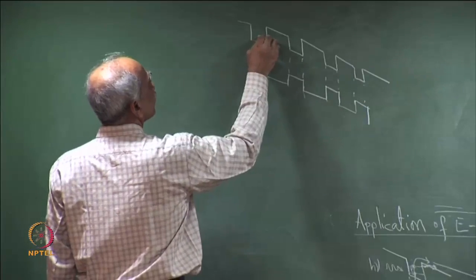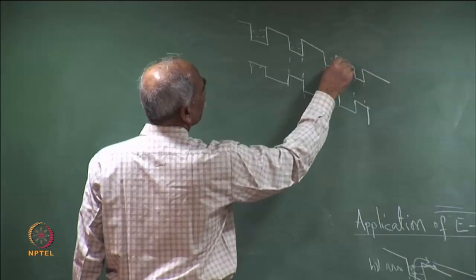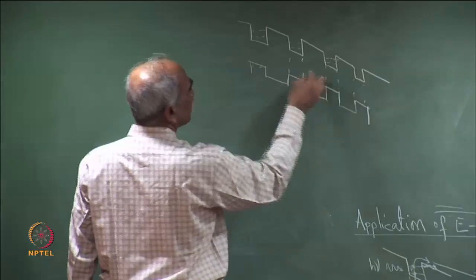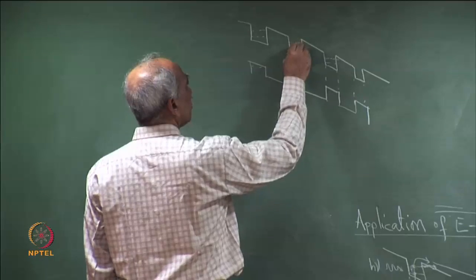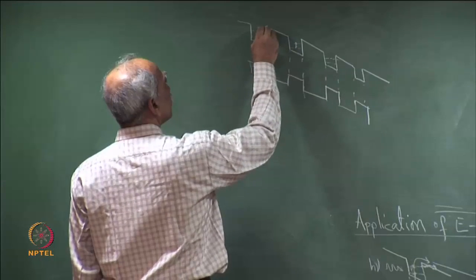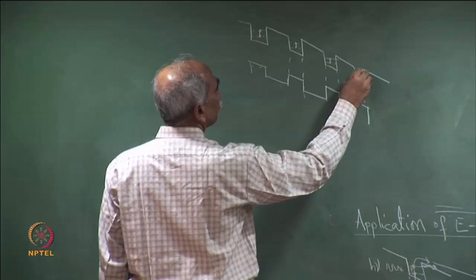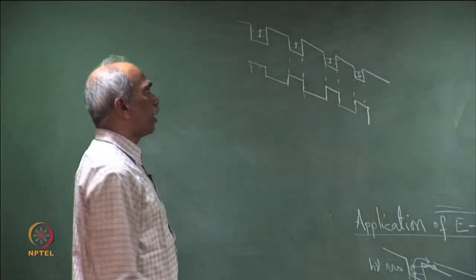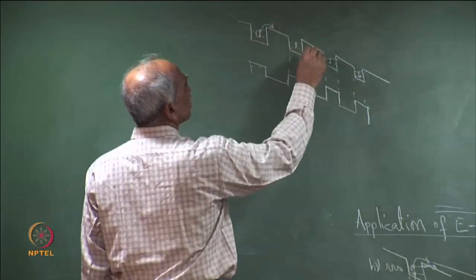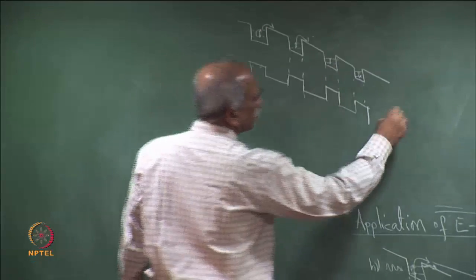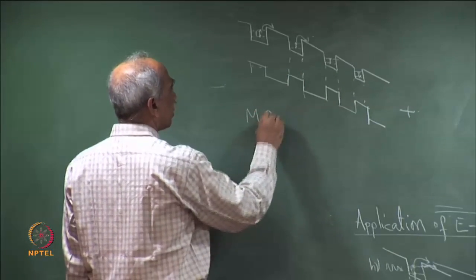so here are the levels. In each of the wells we have the same energy difference, provided they are identical. If the well width is the same everywhere, then the energy separation between the two subband levels is the same everywhere, and therefore photons of the same energy can be absorbed. So, the electron makes an upward transition and then a transition outward. There is an applied potential here, plus and minus. So, this is a multiple quantum well device.